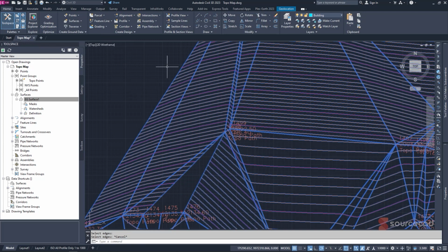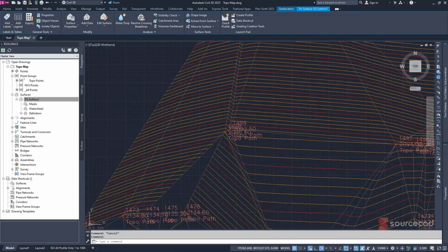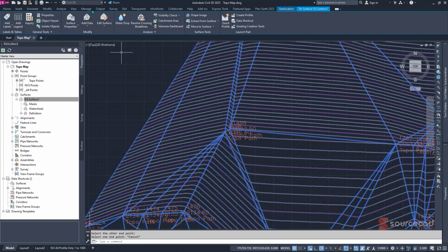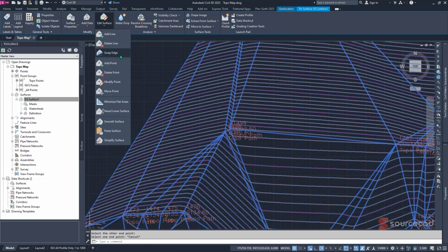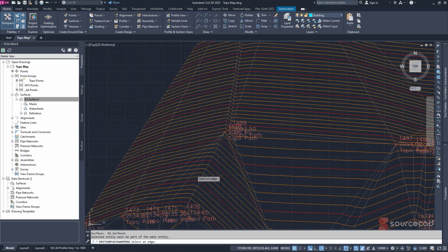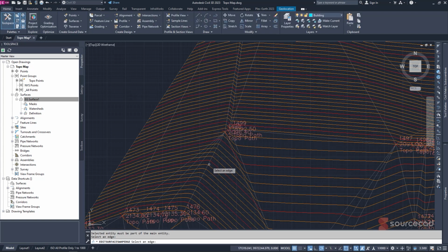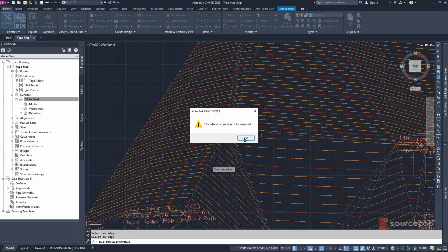And if I want to add it, just the same way, just select your surface, the contextual ribbon will show, click on add line. So from this point here to that point, and just like that, that's the way you add your line. Not only that, you can also swap your edges. So you can click on swap. So if you do not like how this one is, you can click on it and it can be edited or it can be swapped.